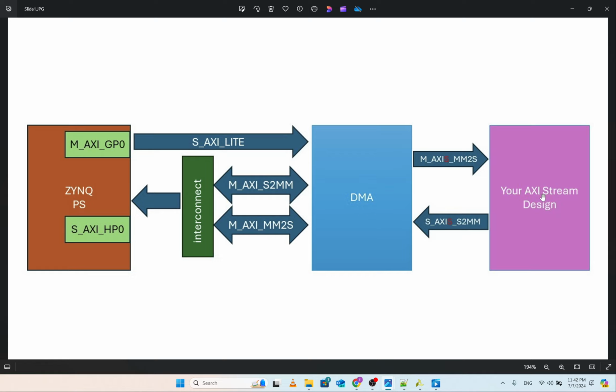And the reason our device uses AXI stream is due to the fact that it is a simple interface when it comes to controlling it, and it allows large bursts of data transfers, which is crucial.